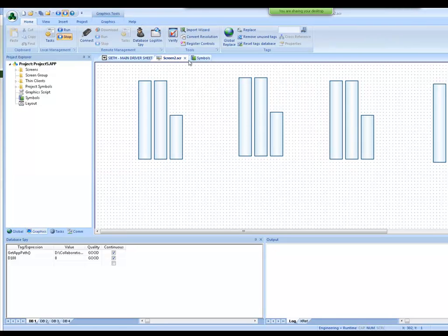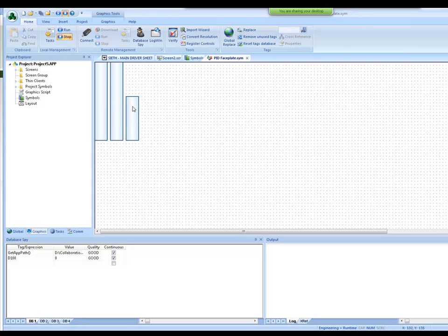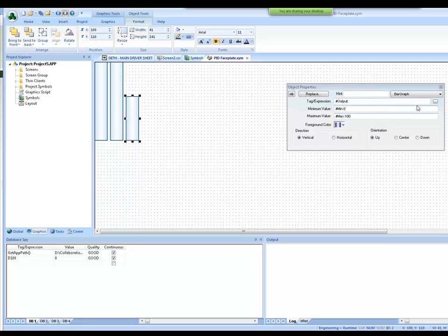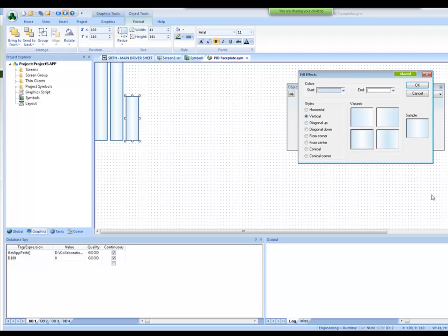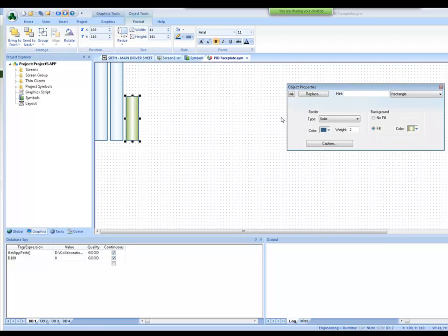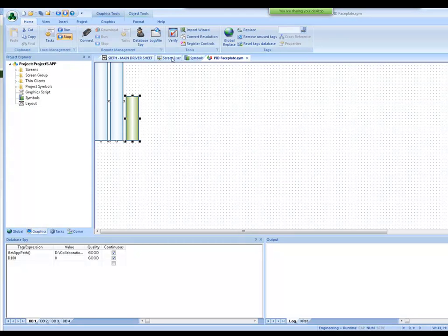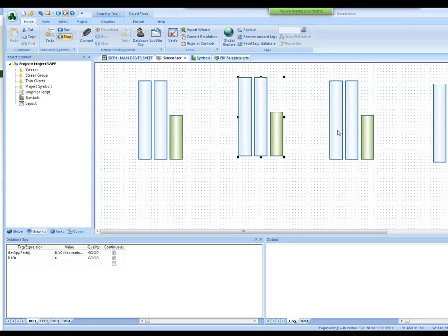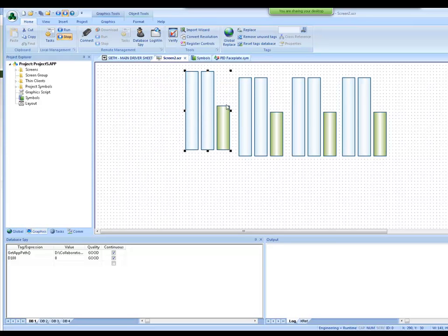And if I modify, let's say I'm gonna modify this, right click, edit the linked symbol. So I'm gonna do something very easy to see. If I go here on the rectangle and change the fill, instead of blue, I'm gonna have green. So we can see this specific rectangle with green. As I save it, I just save the master symbol, and everywhere I'm using that symbol, it was modified. So you create the faceplate just once, and you can reuse it in all your project. Okay.